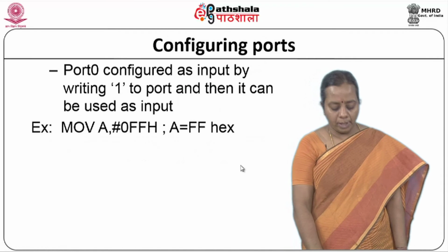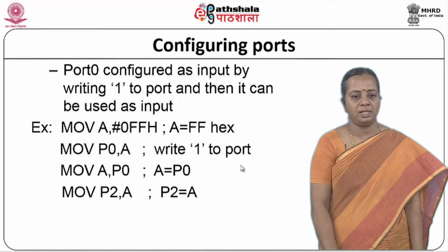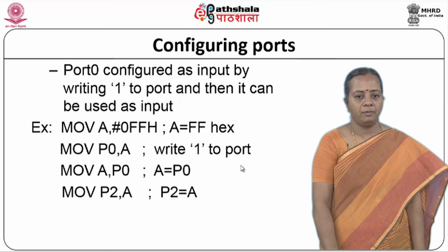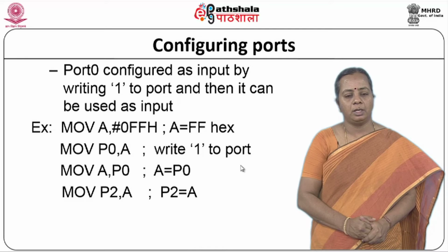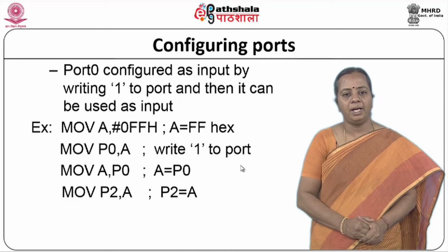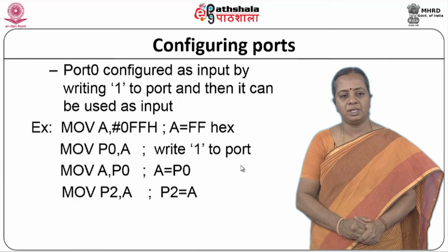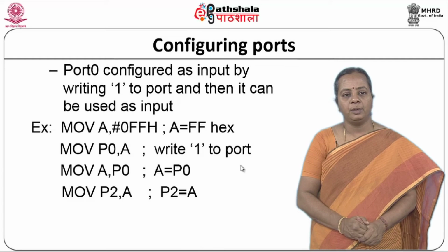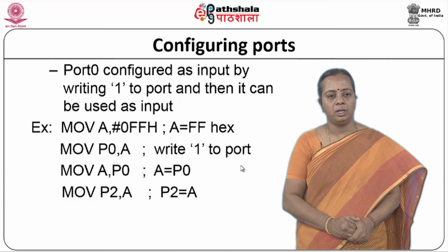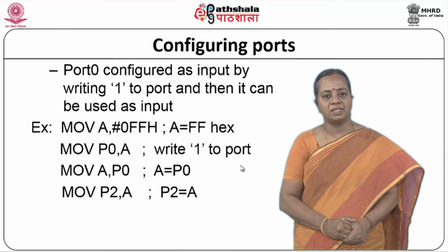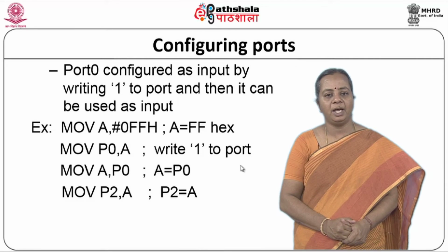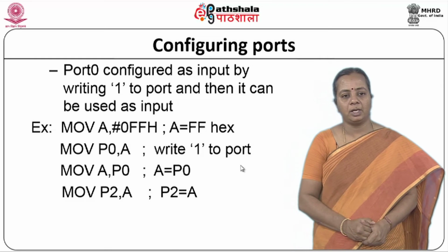This is a simple program segment where I configure a particular port as an input port, and I will be reading it. Now, you just see that this is an example, a part of a code, where I can see that port 0 is configured as an input port by sending eight ones, rather I can call it FF.